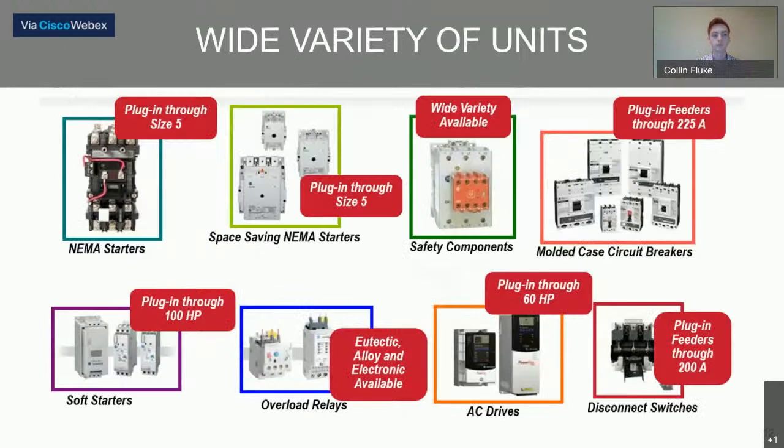Now, what can you put in an MCC? You can put everything from NEMA starters to molded case circuit breakers, VFDs, soft starters, transformers, lighting panels, just about anything you would have running a motor in your plant or feeding power anywhere in a plant.